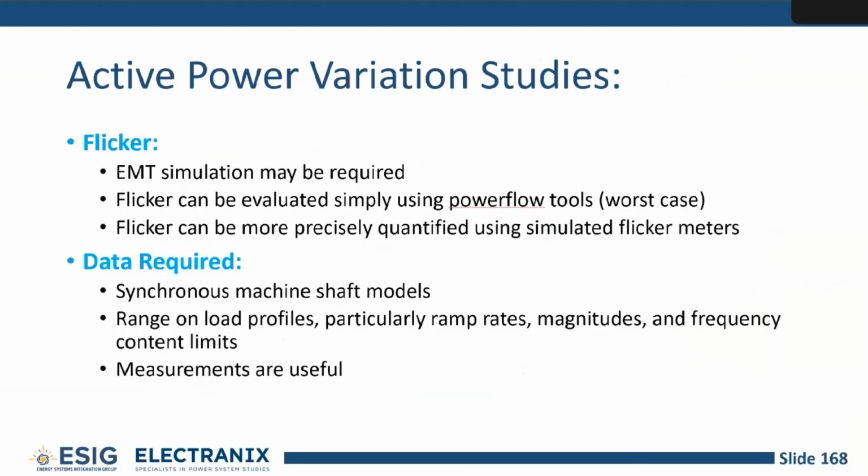And so we've seen mitigation for these things, including for large loads. The large load does cause a flicker problem in LEDs. And then the solution is you go and just change all of the lights to a higher quality LED. But what voltage was that? It's really a little hard to do a flicker study based on the old standards because we don't really know what for that region is going to be a problem. But it is something that's not that hard to study, and it's also maybe not that hard to mitigate.